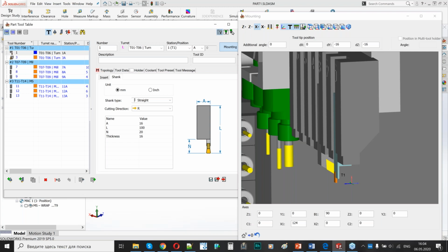You will have to apply counterclockwise, or M4 command, for the direction of spindle rotation, but other tools in this section, OD turning tools, will need M3, or clockwise rotation direction. That means you will have to stop your spindle to perform the cutoff operation and then turn it on and change the direction of rotation for each part.